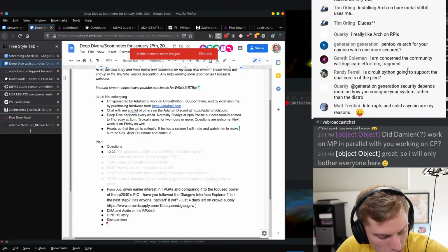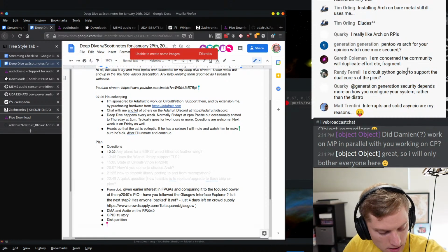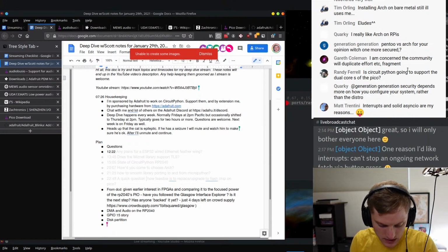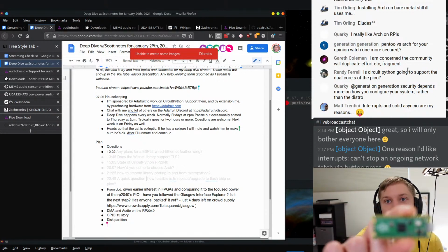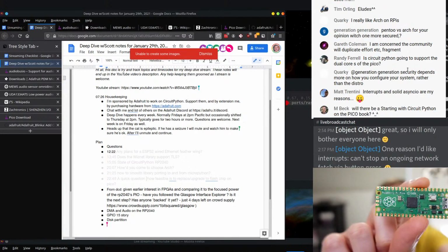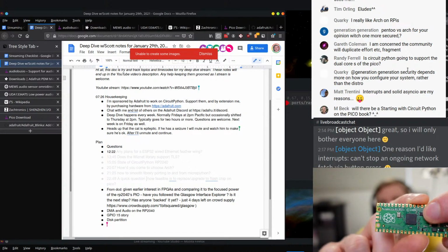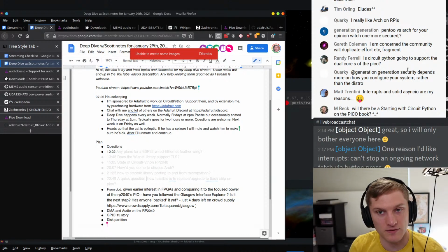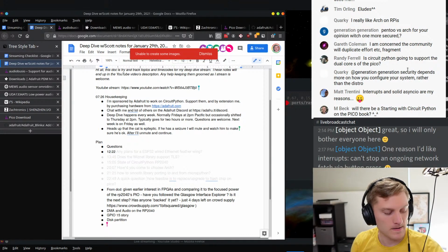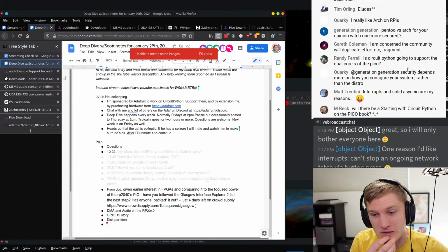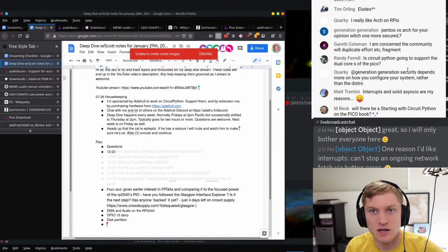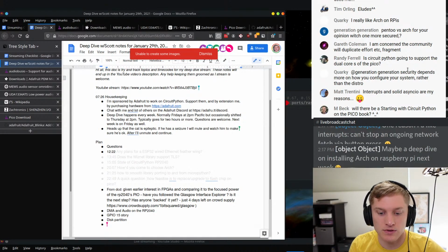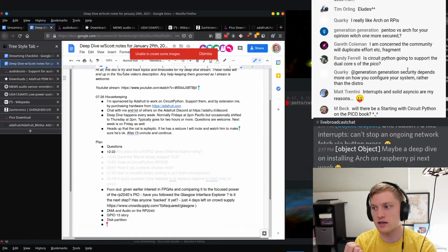I think it'd be pretty hard because the chip is really small. It's very tiny. The flash chip is this chip here, and it's not a large one. You're definitely going to need a hot air gun. And if you have a hot air gun, you could probably do it. But software wise, you'll need to change the size that everything is. But yeah.